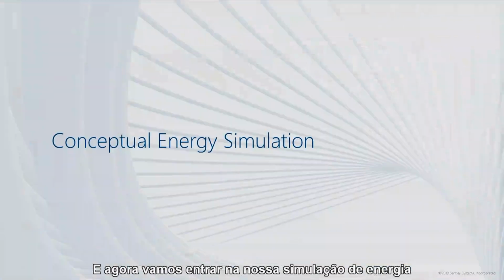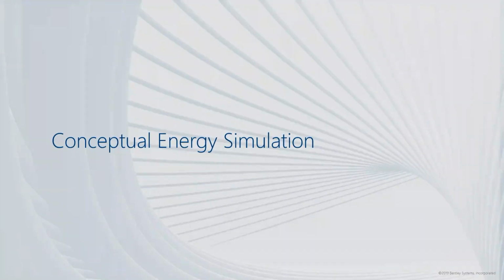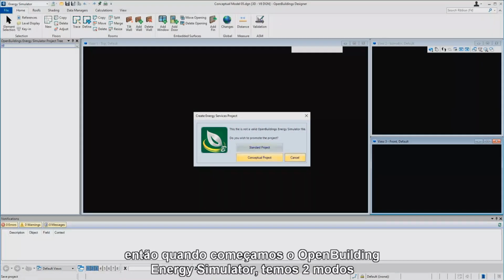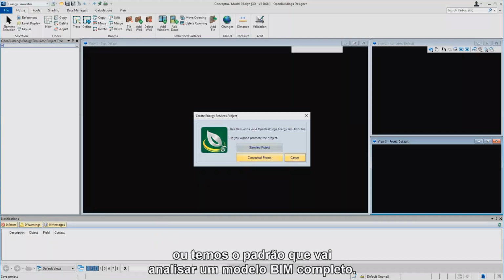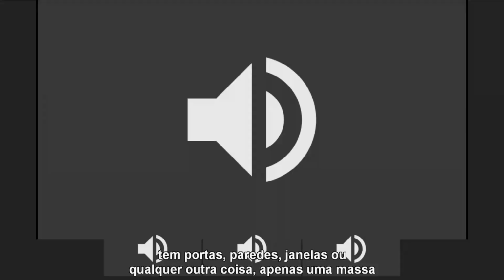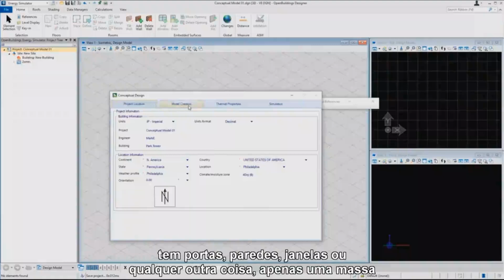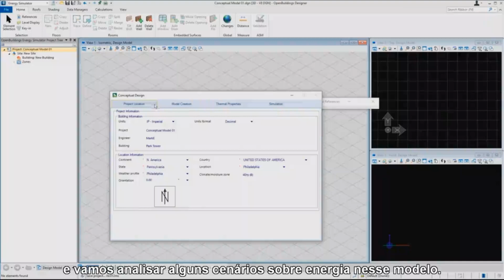And now we're going to go into our energy simulation to bring in our model. So when we start OpenBuildings Energy Simulator, we have two different modes. We have the conceptual modeling mode, which I'll be showing you now, or we have the standard, which is going from a full BIM model. But what we're going to be doing is taking that massing model that we started, that has no doors, walls, or windows or anything yet, just a massing, and start applying some scenarios about energy on that model.